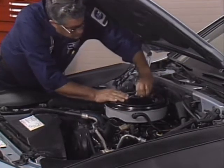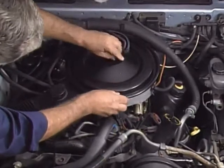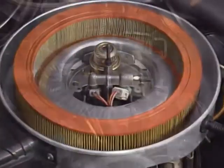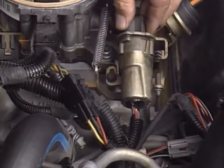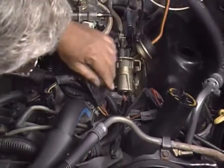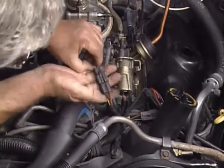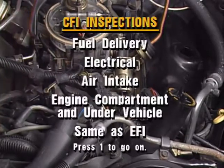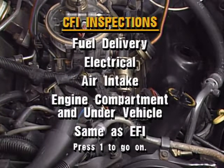Also, you'll have to remove the air cleaner cover to check the injectors, connectors, and the fuel pressure regulator. Finally, most CFI systems have an idle speed control motor. Check this motor to see that it's securely mounted and that its electrical connection is clean and tight. Now review CFI inspections. Study each frame and press 1 to go on.